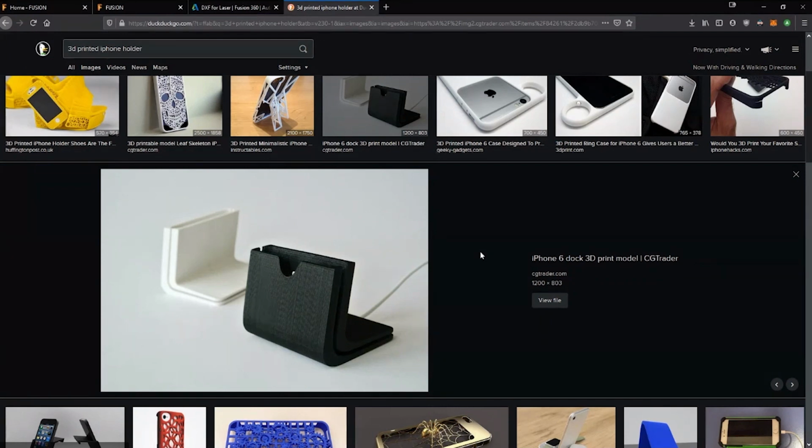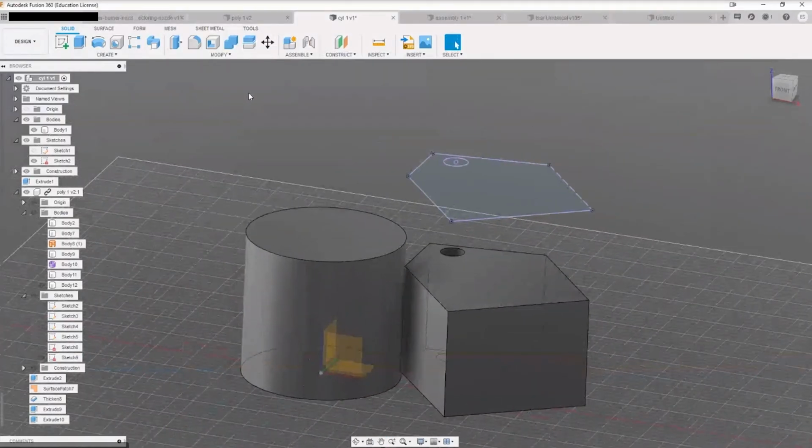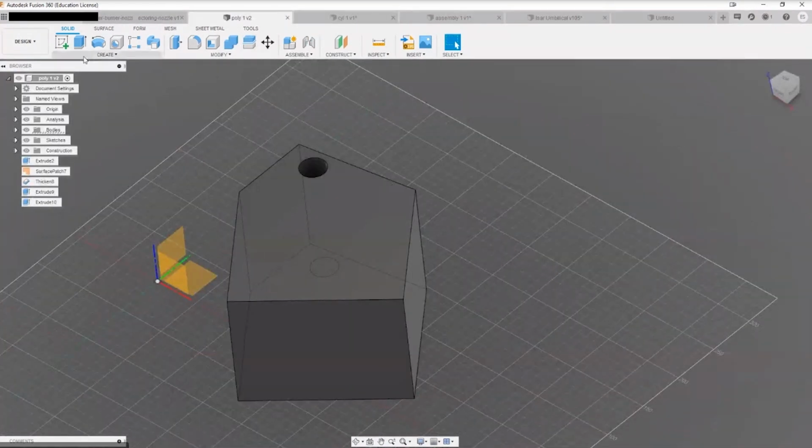Okay. Any more technical questions that I can cover now? Maybe something that is on the top of your head, but might make your life a lot easier starting out. Not so much a question, I just wanted to add a bit. If you go back to the dimensioning, there's 2 things I want to mention. One, if you click on a random line, instead of having to break out the ruler tool, it gives you a little readout of the length of the line on the bottom right. So that's kind of handy.